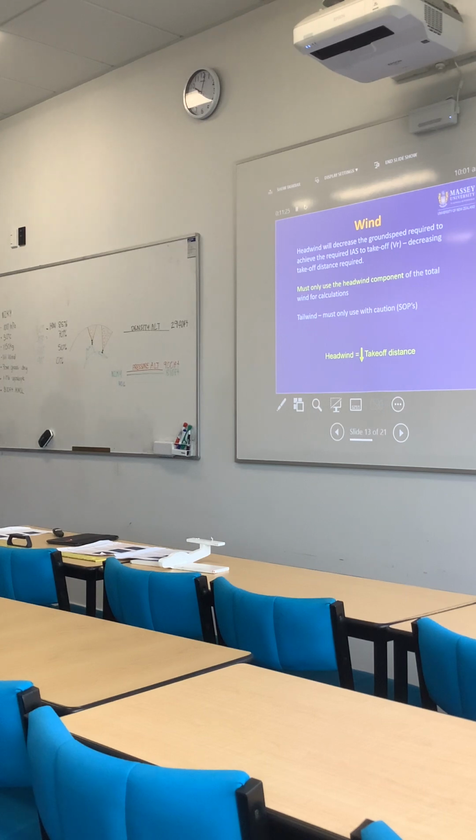Okay, so that's wind. So again, to read through what the graph is showing you, put your example on there after calculating it. I think it says nil wind, doesn't it? So teach them how to account for nil wind. And then at that point, after filling out the wind, you can have a bit of a discussion on the difference between the distance to just get airborne and the distance to 50 feet. Highlight how much of a difference that is, because honestly, sometimes it is almost double the distance required to just get airborne. So do point that out to them.